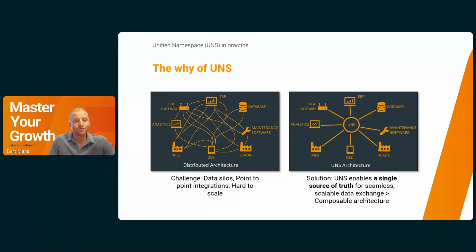Well, let's start with the UNS itself. So why are people interested in setting up a UNS? As we can see on the left side and the left image, most companies have a distributed architecture. There are many different systems that are all integrated with one another. We have what we call point-to-point integrations. So a database talks to an OE application, a SCADA talks to an ERP system, a MES talks to an ERP system, and all of them interact one-to-one. It's really hard to scale, as you can imagine, because let's say we need to replace the SCADA system. In this architecture that we see here, it has 3 connections, which means that we really need to redefine those 3 connections.